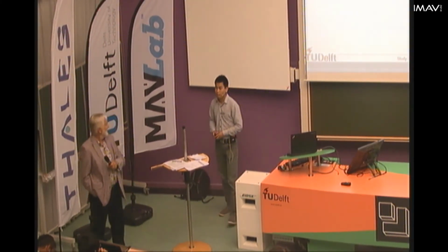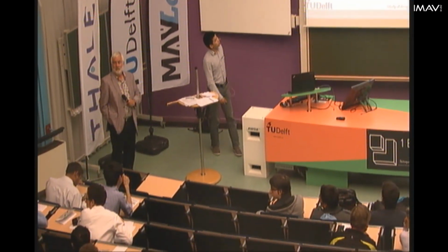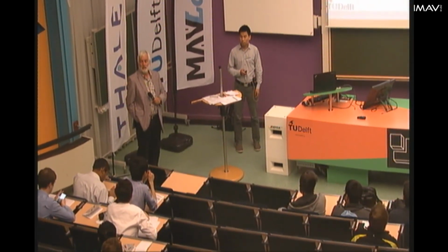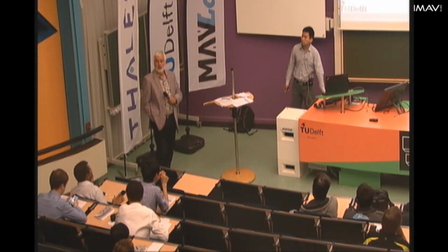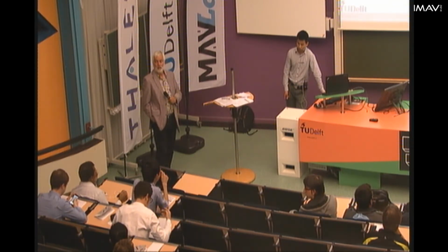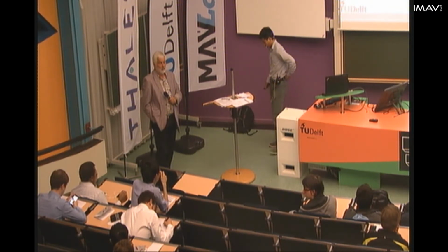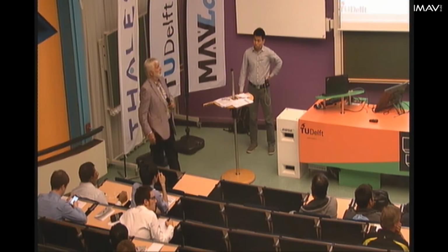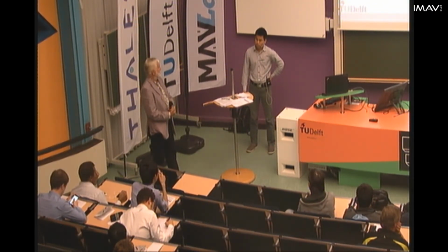Hi. Thanks for your presentation. The question I want to ask: in your initial design, you used the quasi-steady aerodynamic model to estimate the force and power. And you considered the translation, rotation, coupling, and also the added mass. But in some cases for flapping wings, the unsteady aerodynamics really predominates the aerodynamic force generation, like the wing capture, the shedding, and the generation of vortices. So have you considered the accuracy of that quasi-steady model?